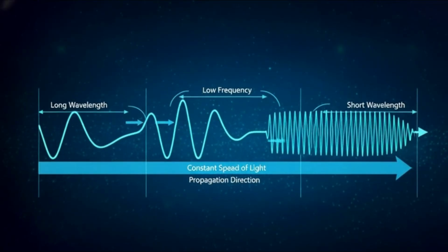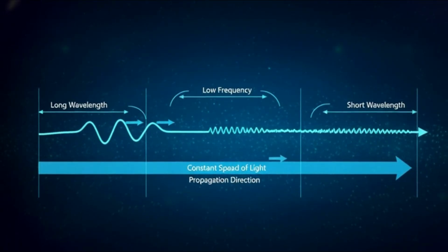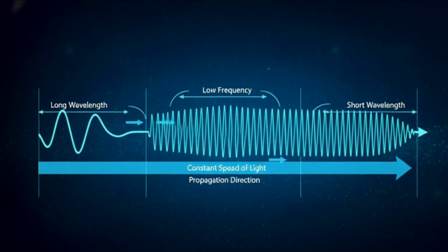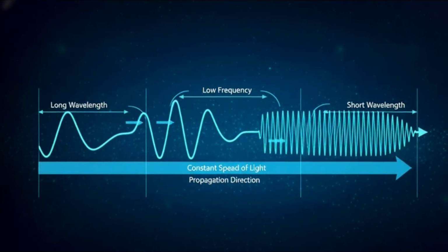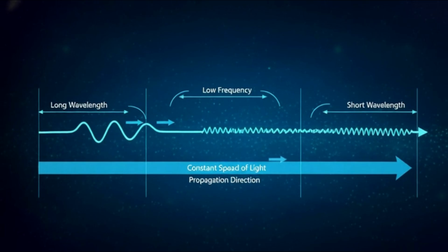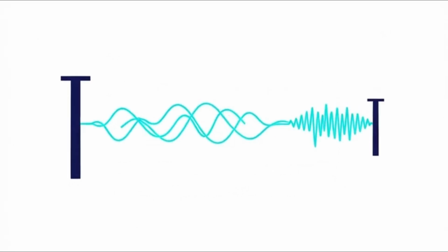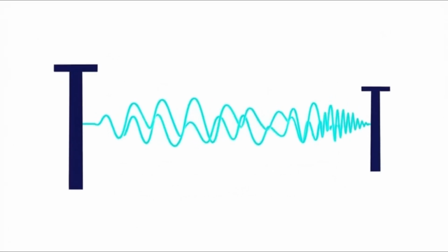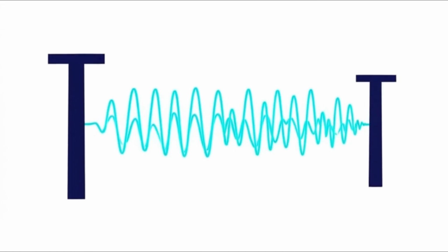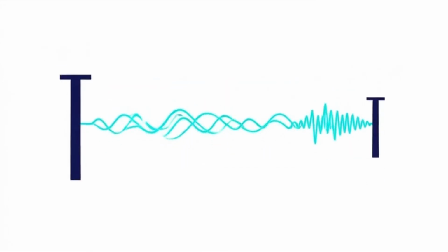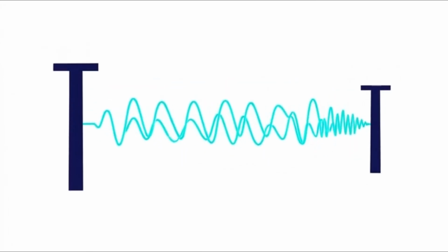In the RF world, everything is a trade-off between two things, frequency and wavelength. They are tied together by the speed of light. As frequency goes up, the wavelength gets shorter. This is why your 160-meter ham radio antenna is massive, but your 5 GHz Wi-Fi antenna is tiny. Understanding this relationship is the first step to mastering RF design.